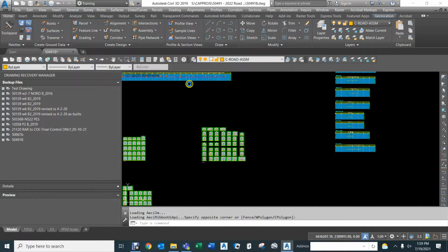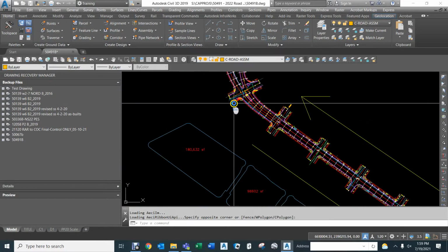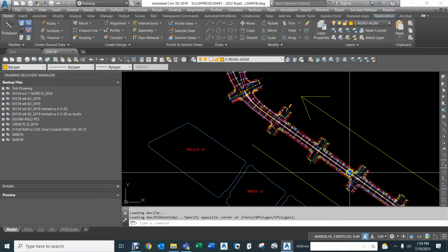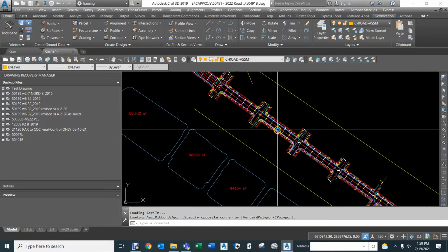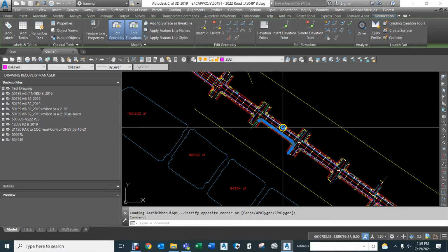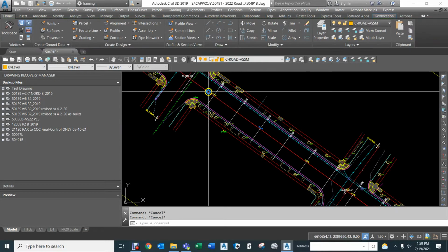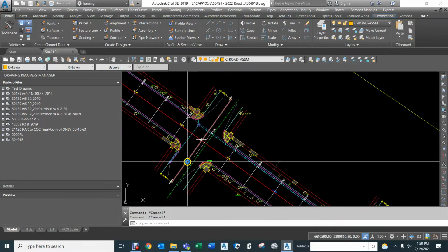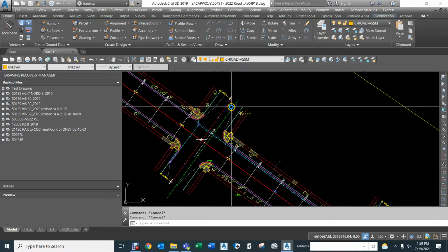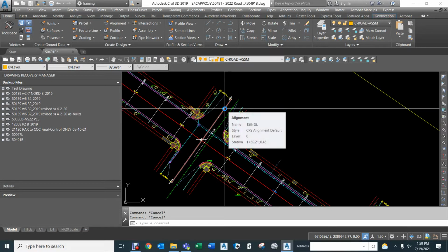So we're done with the center line, and the first thing we want to do is work on the center line of the road, get it done, and then attach it to the existing lip of gutter, which is done. And now it's time to go back and apply some other techniques, kind of similar to that, to the side streets so we can finish up our intersections.